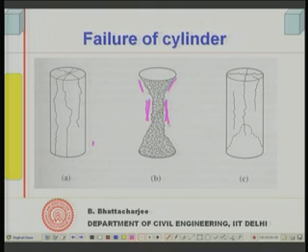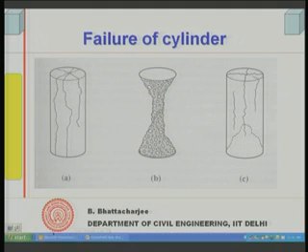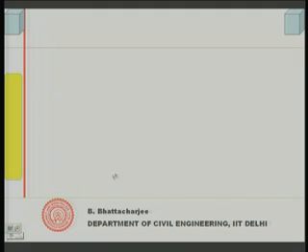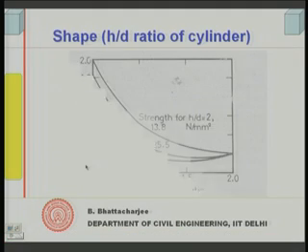In fact, in this portion you do not have any effect of the restrainment due to the plates. So, Platen effect is not there in this one. In this zone there is Platen effect, and one would see the crack formation of this kind.